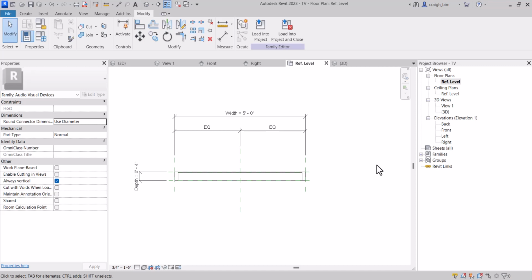So now that I have one family as the monitor, I'm going to create another family that can become the mount. So let's say that we want a mount on the wall, and it's just going to offset from the wall. You know, I would just offset the family from the wall and not really have a mount. But if I want an angled mount so that I can show the television or monitor that's like 45 or 60 degrees off of the wall, because it's going to be in a big conference room and it's going to take up the corner, then I'd like to show that. And eventually it would be nice to schedule that or get a price for it or just be able to coordinate it. So I'm going to create a mount.